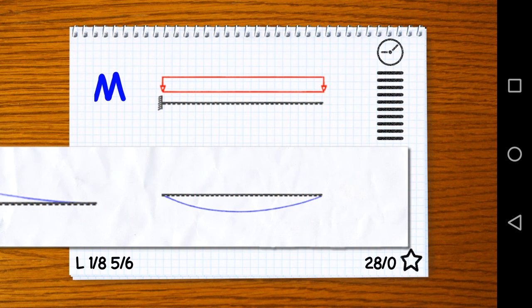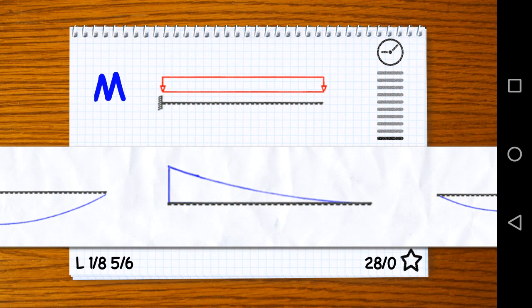Now, how is this system going to deform? On the left side, we have a clamped support. That means that the point on the left can't move at all. On the right side, we have a free end. That means that the node at the end is going to move downwards. And now you can picture how the system is going to deform. We're going to have a so-called positive curvature, as I explained in the first video. The tensile side is going to be upwards, so the moment is this one.